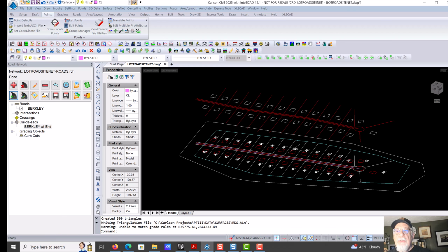And there it does. It looks at all of the 2D lot lines. It finds that they're within the 20 foot that I put for the lane component of the template. It found the pads too, which were within the correct acceptable distance, and it elevated everything to 3D. Which is pretty spectacular, okay? And the whole idea, of course, is as you change your design, you can just keep cycling through.